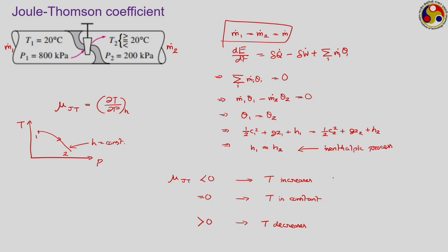So, when the Joule-Thomson coefficient is negative, its application is a heating effect, or when we want some room heating kind of application, we can go for this. However, if our target application is the refrigeration industry, that is, we want a cooling effect, then we have to ensure that the Joule-Thomson coefficient is positive, that is then only we are going to get the cooling effect.